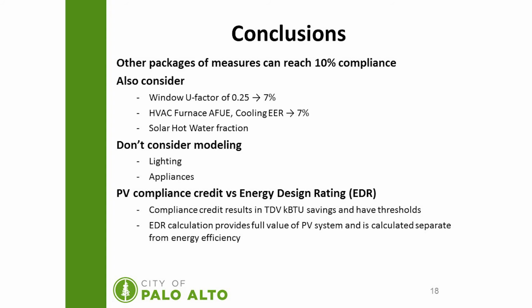This rating is a scaling measurement that shows how your building is doing in comparison to a reference building. PV is given full value in this calculation. The PV compliance credit value that you receive in the model may actually be smaller than the PV system you are installing. The energy design rating calculation takes the full value of the PV system and is calculated separately from energy efficiency.